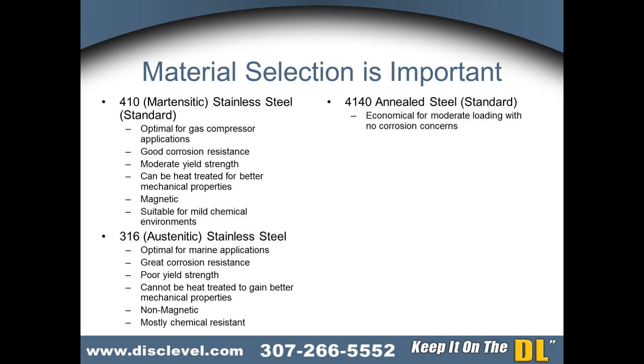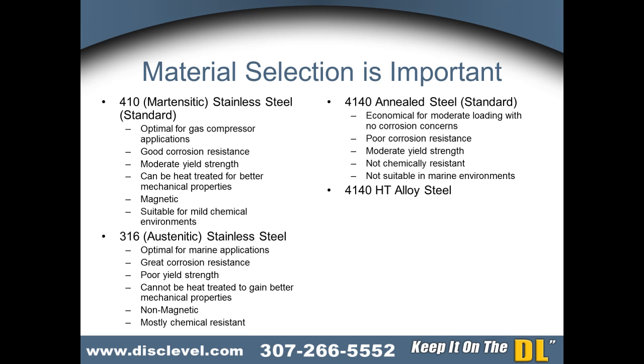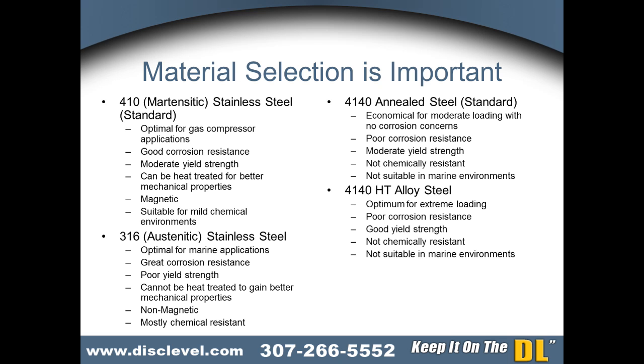4140 annealed steel, standard. Economical for moderate loading with no corrosion concerns. Poor corrosion resistance, moderate yield strength, not chemically resistant, not suitable in marine environments. 4140 heat treat alloy steel. Optimum for extreme loading. Poor corrosion resistance, good yield strength, not chemically resistant, not suitable in marine environments. Other materials are available upon request, so consult us regarding your unique application.